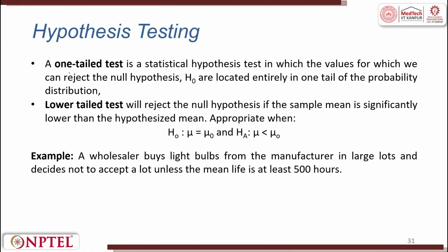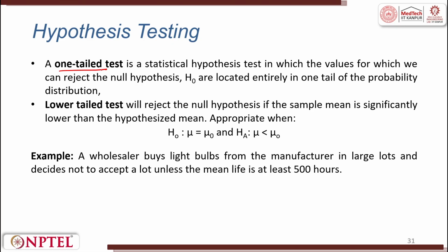The last topic I would like to discuss in more detail is the one-tailed and two-tailed test. We talked about the one-tailed test when we are talking about only one direction, where the acceptance region is only in one direction. For example, if I say the dimension is 2.5 micrometers, and I say less than 2.7 micrometers is acceptable only, that is one side only.